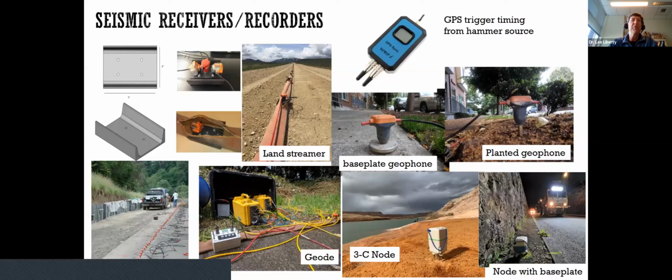You tie all these geophones together typically with something like I'm showing here, a data recorder. These are geodes, again, available through IRIS. These are 24-channel boxes. You can see my little radio trigger box here in the foreground. So when we thump the ground, we record the response.